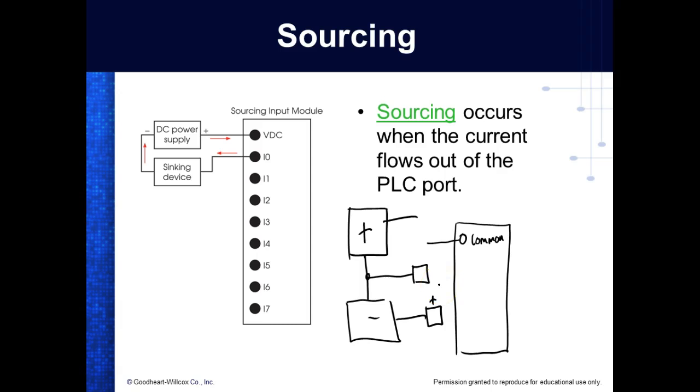So on that trainer, you could take your ohm meter and go between what the trainer calls ground and you can measure it to that little round terminal on your power plug, and it's going to measure infinity. So the trainer does not run a true ground; it runs what they call a common. So even in the trade, they misuse those terms. Normally, what ground should mean is that somewhere the system is referenced to earth ground. And this right here would be labeled minus.